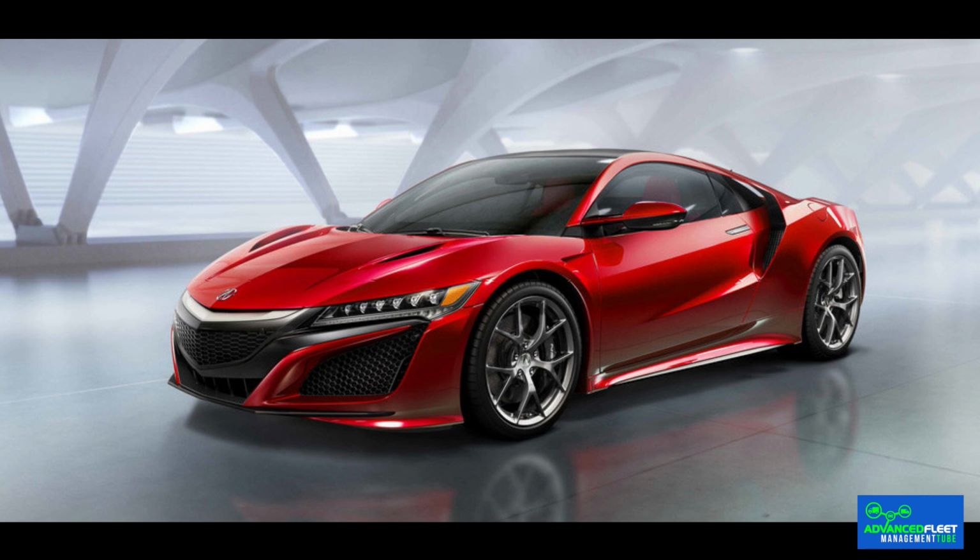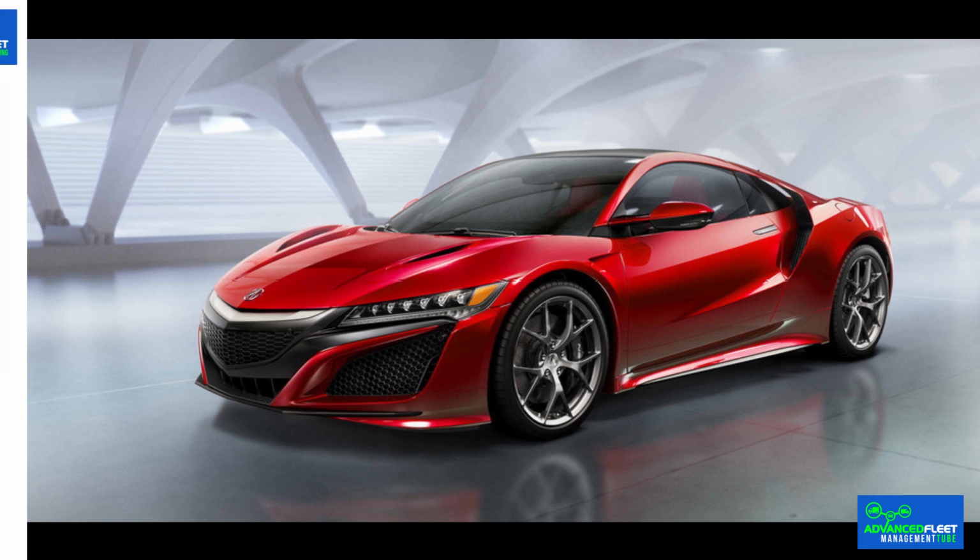In the case of the Honda NSX, an innovative approach has been implemented by incorporating 2 smaller electric motors on the front axle, instead of relying on a single motor. In this way, the torque distribution and regenerative braking function is significantly more efficient, as each of the 2 motors can operate independently of the other. While one sends power to the wheel with the greatest traction capacity, the other applies regenerative braking.